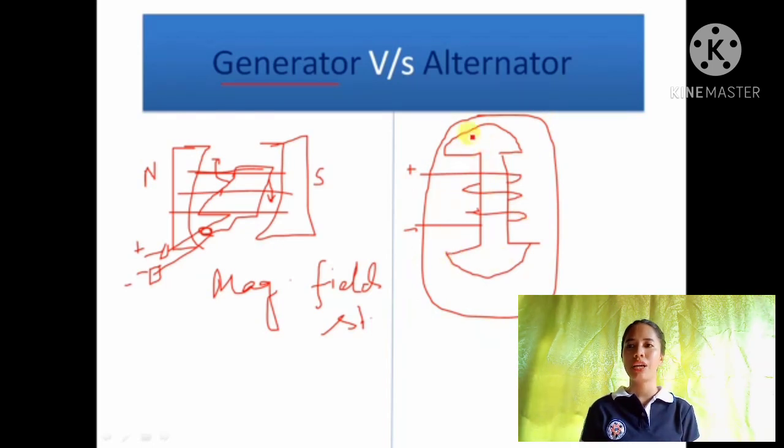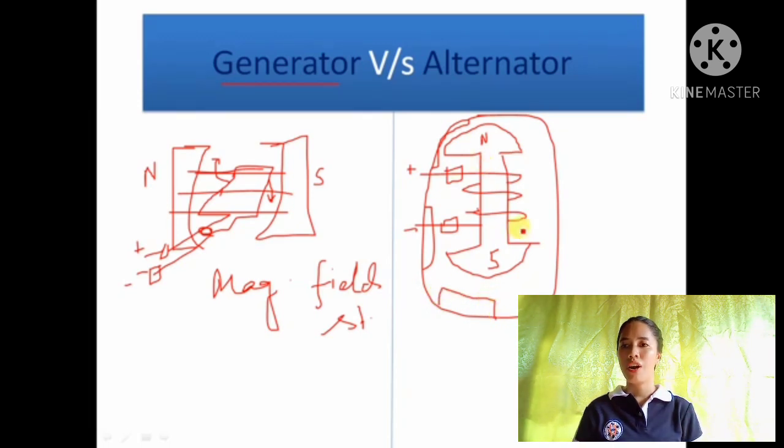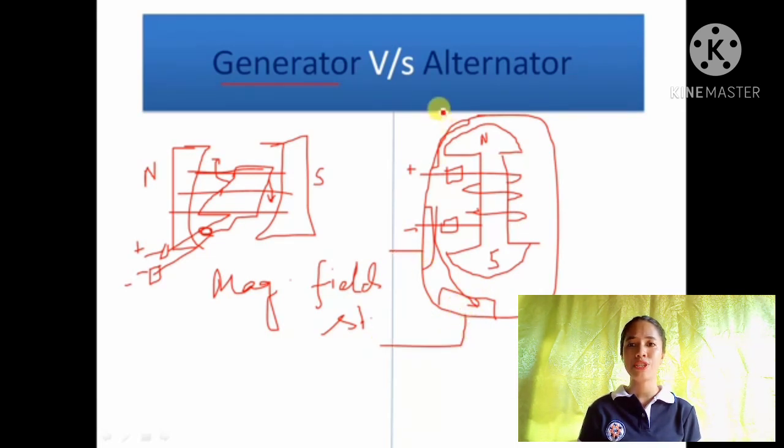This is connected, of course, through brushes. So the exciter is there, and it gives the rotor a certain polarity, north and south pole, and here on the stator remains the stator conductor. Here you can see the three phase conductors. So when this magnetic field is cut by this conductor, electricity is generated in three phase.